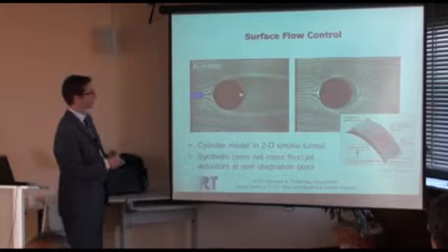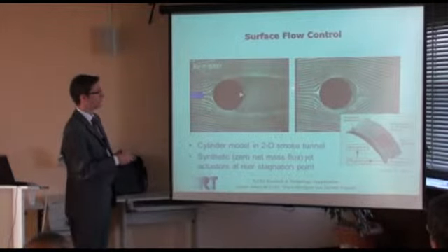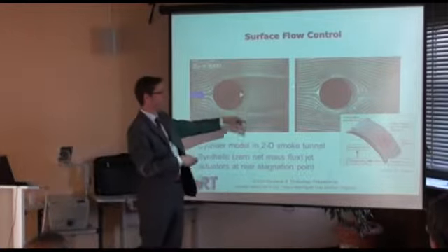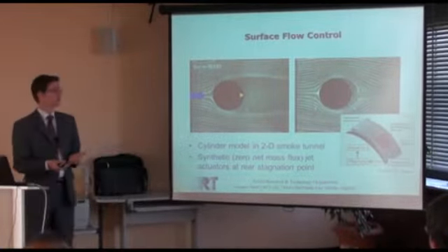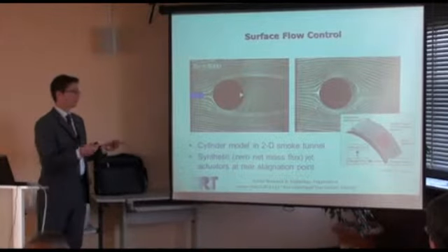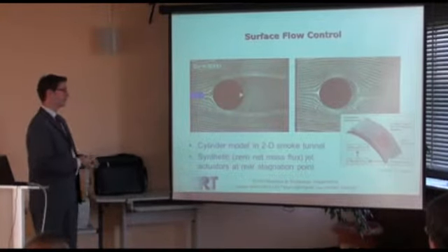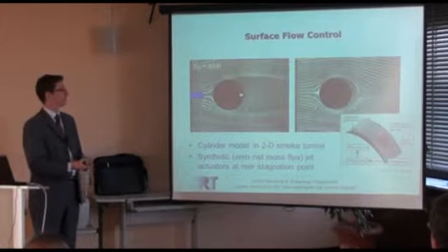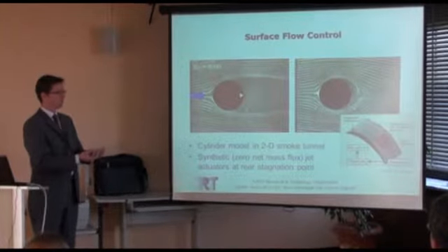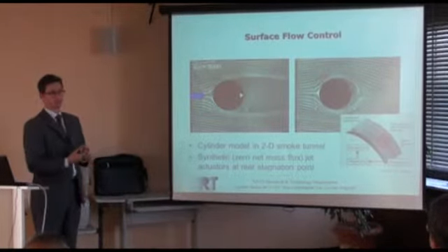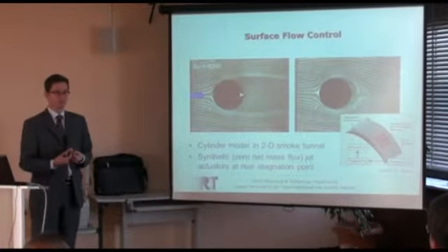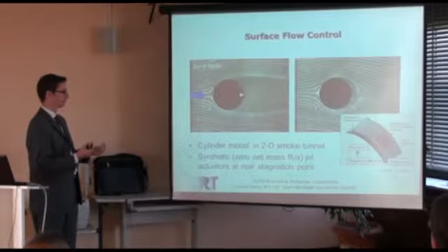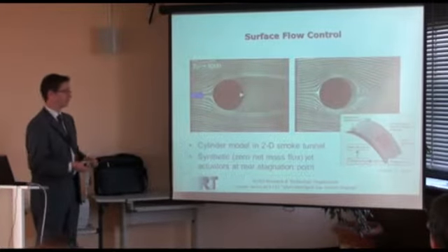And so in the end, we will see a reduced wake. If you compare this distance with that one, therefore very low losses. In this experiment, this is done with a synthetic jet, which means, again, a blowing and a suction done at the same time, oscillating around the mean of 0. So the net effect would be 0 mass loss.